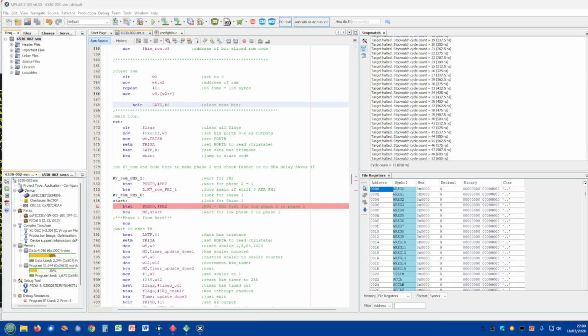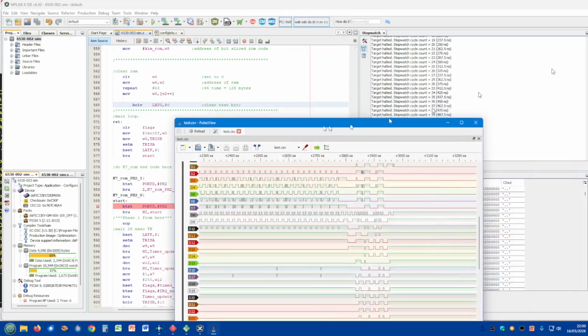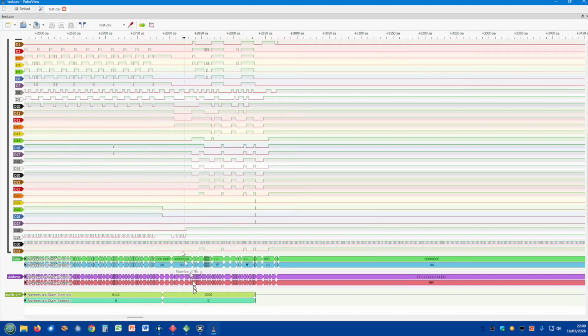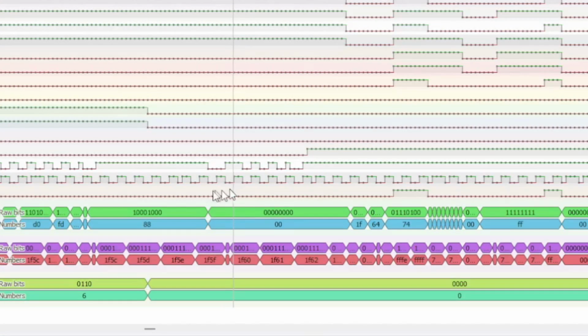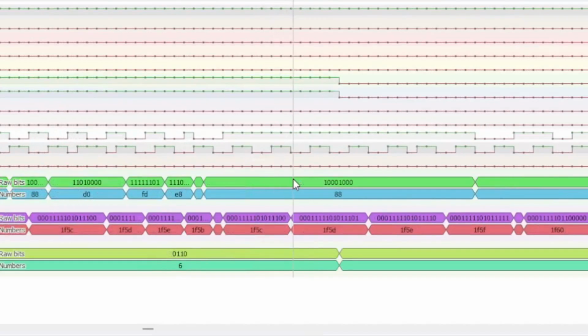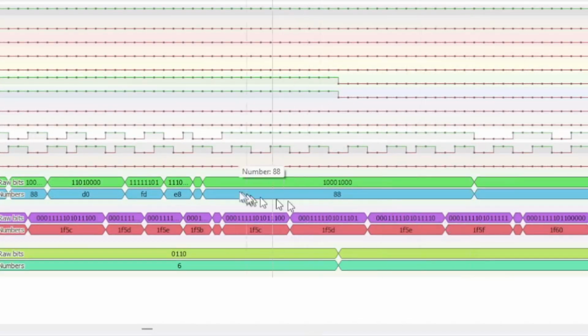If we have a look at this, this is the crash we just had. We zoom into the crash. You're just here where the bus jammed. This bit here is turning the tri-state data buffer on and off. You notice it stays on, and that's when the data bus sort of just sticks where it is.